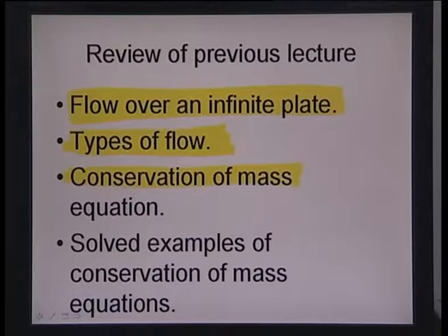And then we did some solved examples for ascertaining the velocity component or the density with respect to time or space, for compressible and incompressible flows. Again, to reiterate, compressible flows are those where density changes with time, incompressible where the density does not change as a function of time. So today we will try to derive the conservation of momentum equation, which is also the second Navier-Stokes equation.